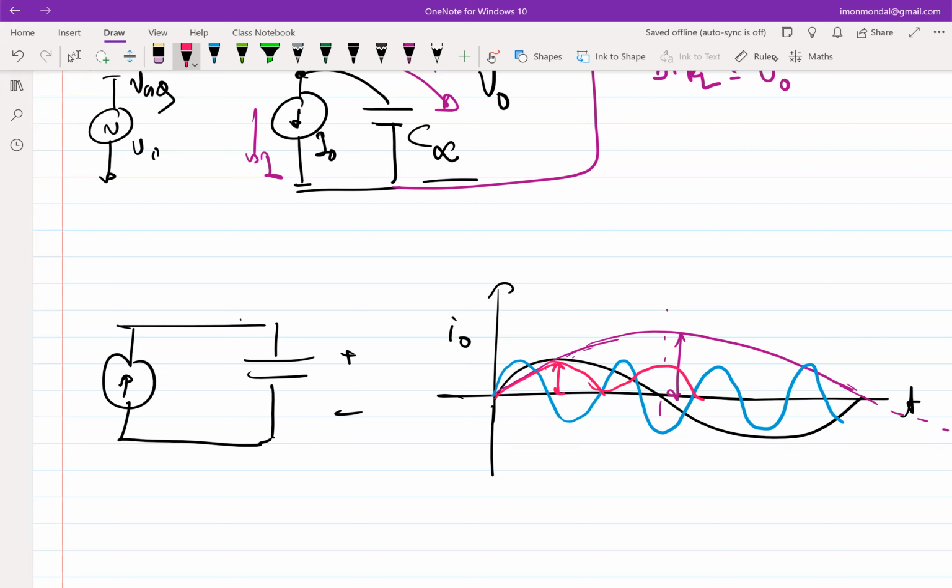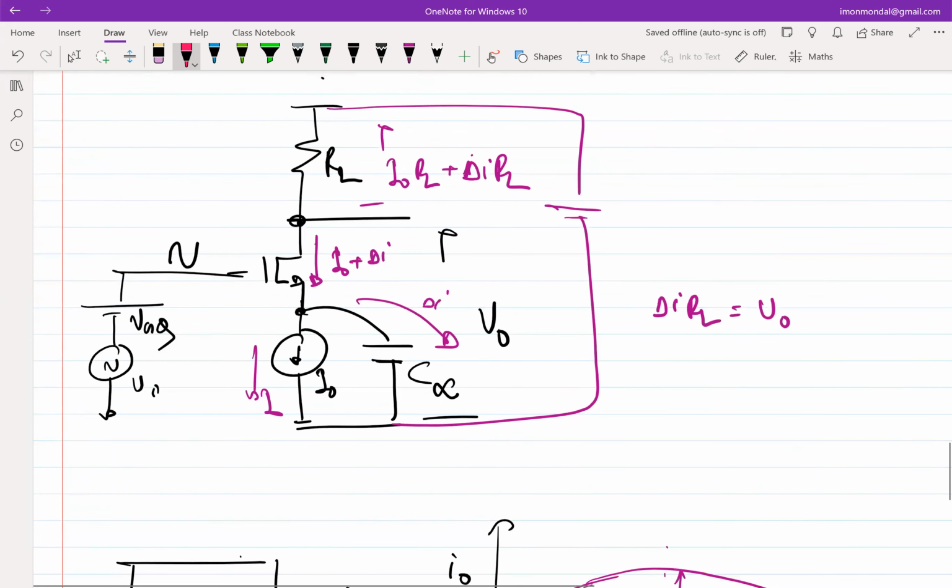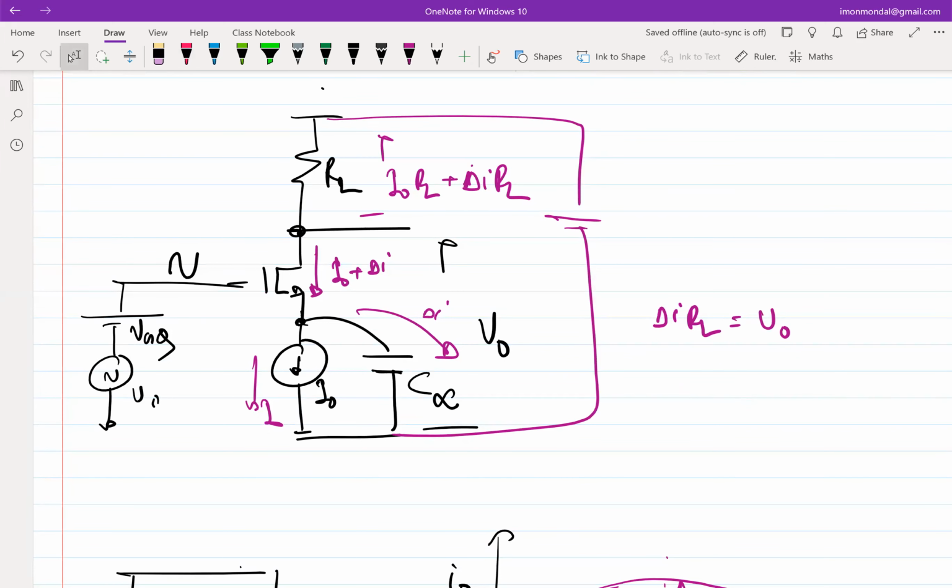The converse is that if the capacitor is large enough, then this effective build-up itself is small, which means the voltage across the capacitor doesn't change within that limited amount of time. That time is the important thing, and hence we call the capacitor a frequency-dependent element, because the voltage across the capacitor doesn't really get accrued if the frequency of the current that you are pushing in is very high. Okay, so that's essentially the way of analyzing and coming up with basic topologies of circuits. We'll stop here and we'll meet after the mid-sem break.